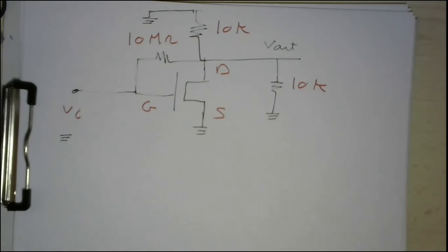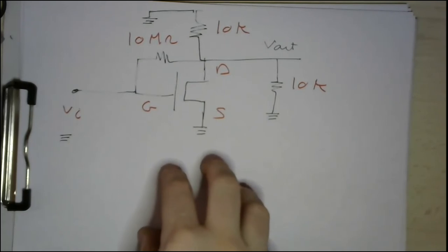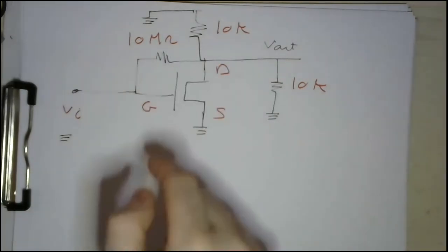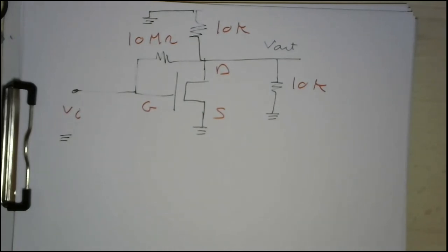Okay, perfect. So in order to solve this AC circuit, we have to return to what we call the small signal circuit model. Please don't forget this model with a voltage dependent current source. Now in the second or the bottom half of the page, I am going to reflect this MOSFET onto a small signal circuit model. So the first step, as I mentioned, is to reflect this circuit into a small signal circuit model.